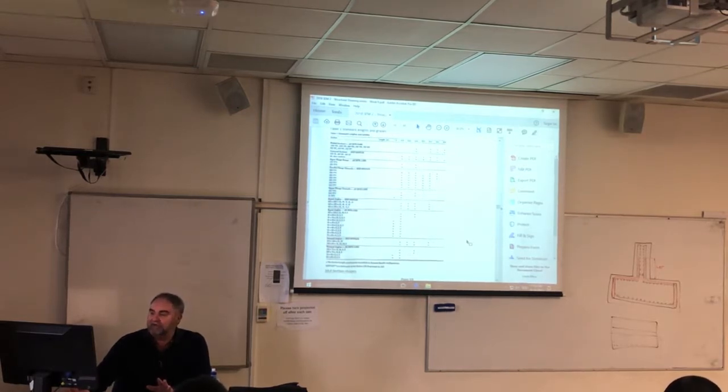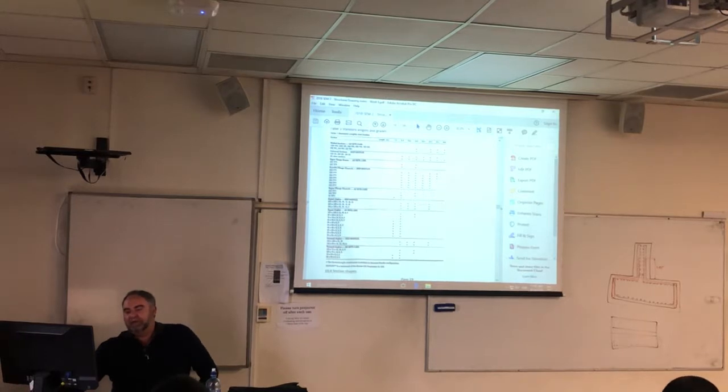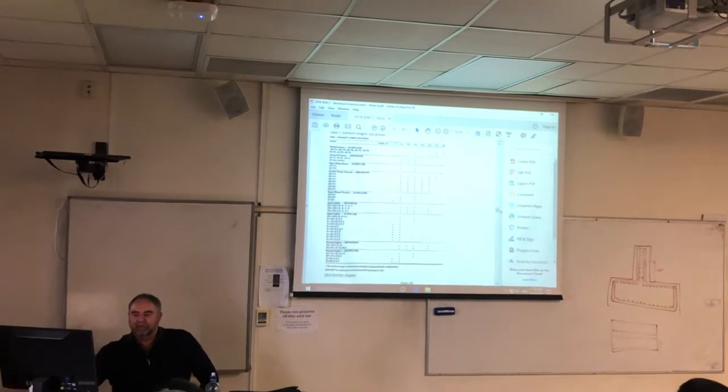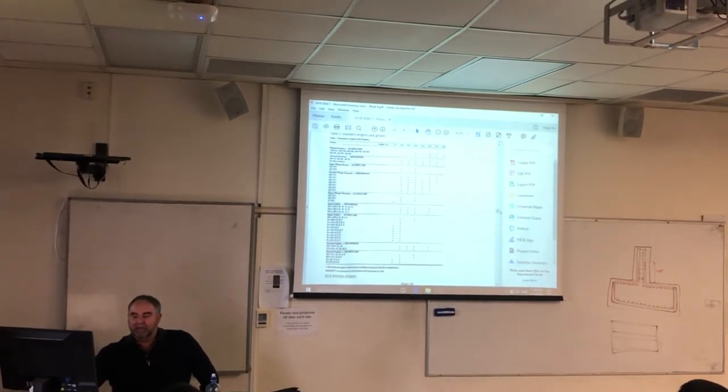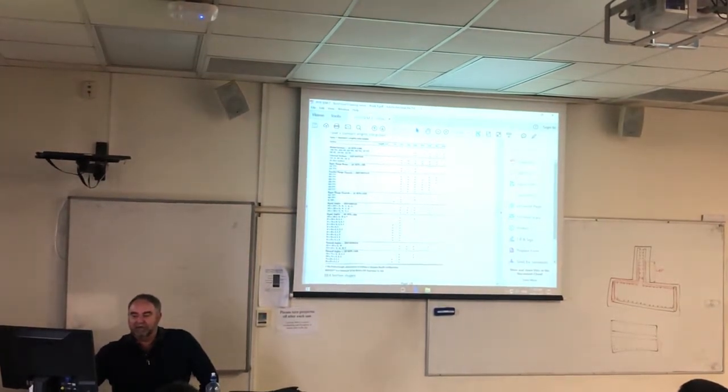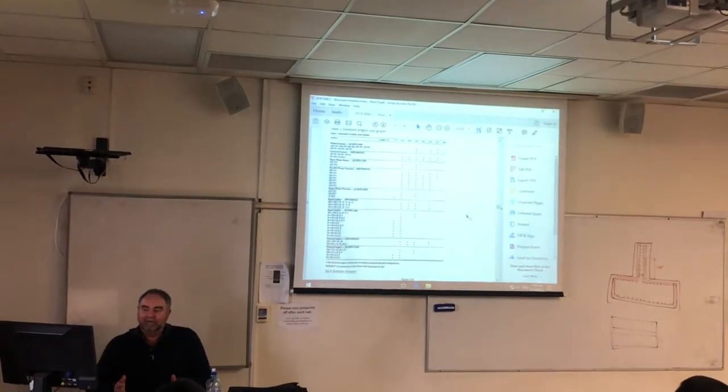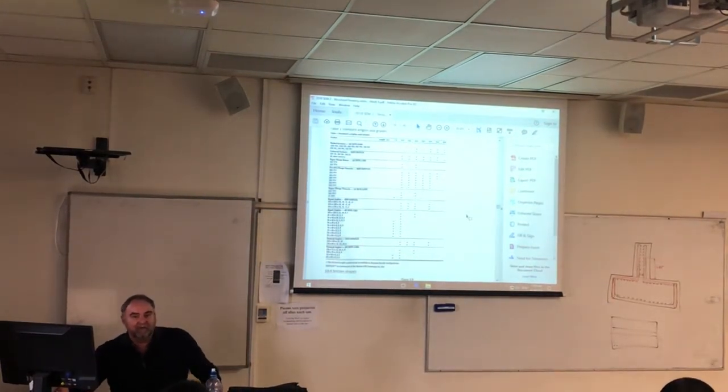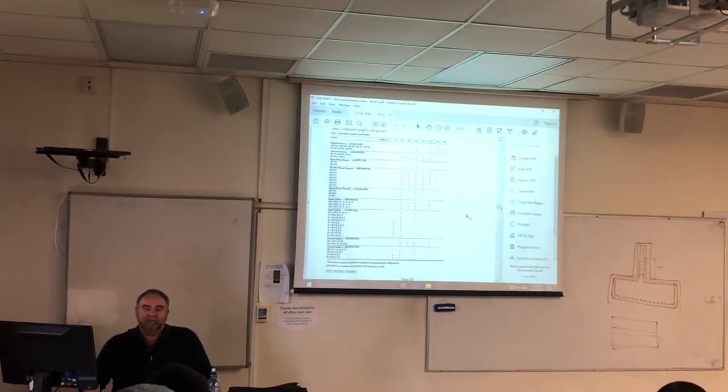If you're in the process of designing, for example, a building that's 7 meters by 7 meters, then you can look at this, and their smallest one is a 7.5 meter member. If that is the one you've chosen, that's fine. But you might as well make the building another 0.5 longer, otherwise you're going to pay for them to cut that down to the right length. So a cost factor comes into play, and it's often to do with the length supplied.